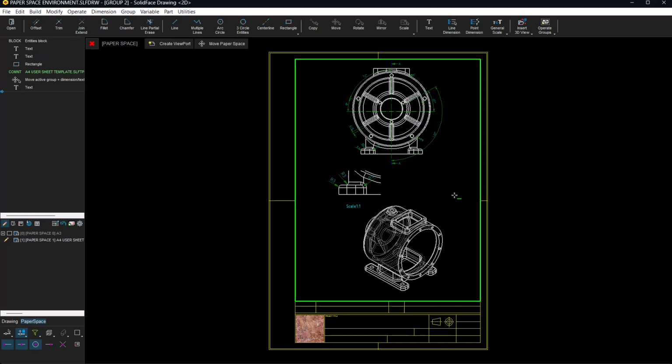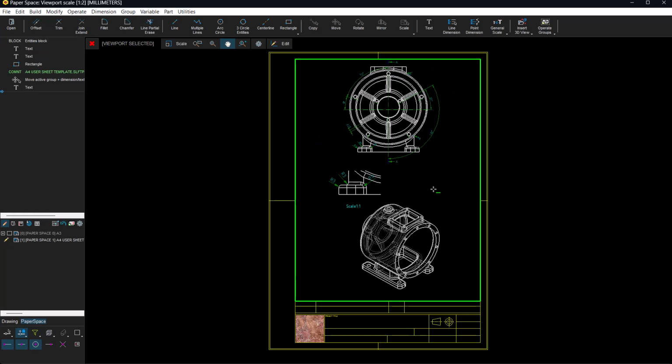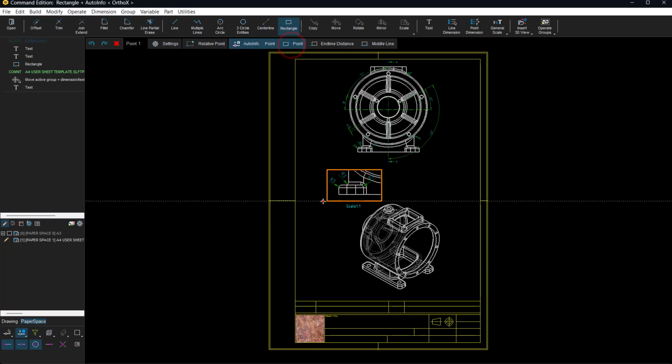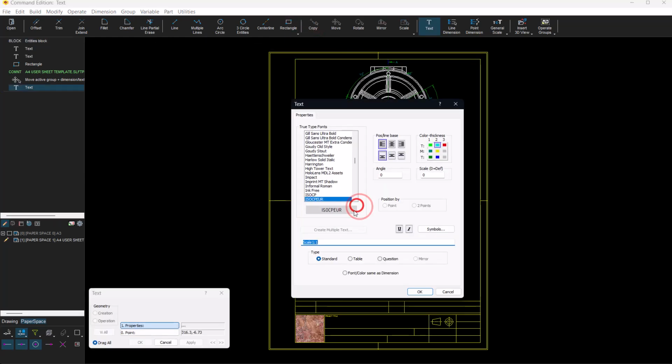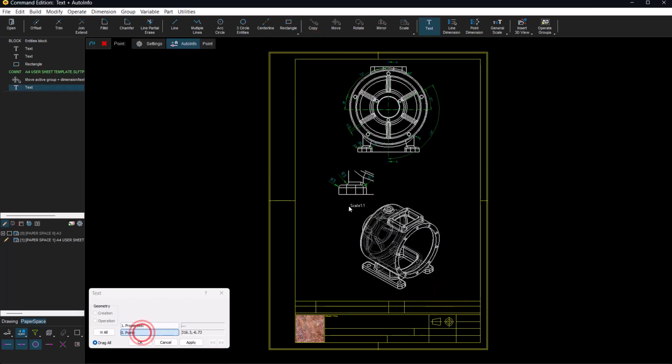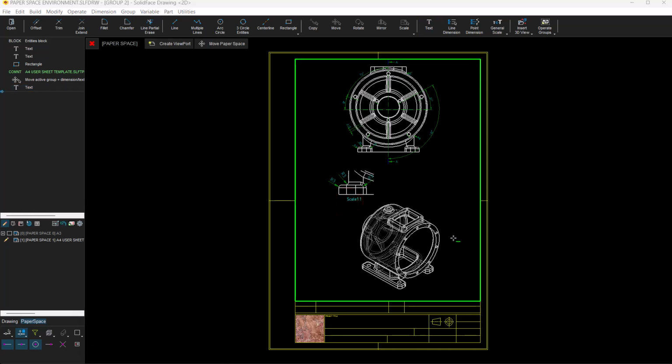The rectangular areas of the viewports are fixed, and if we edit the view from the main viewport, we usually need to edit texts or viewports defined after the main viewport. Let's pan the main viewport. The blank viewport and text must now also be repositioned. Fixing the blank viewport. Repositioning the viewport scale 1-to-1. Defining geometry, texts, or blank viewports must be the last operation so that we do not need to edit it if the main viewport is modified.